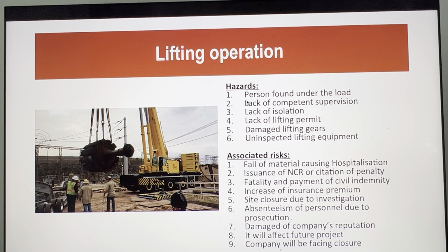In lifting operation, you have person found under the load. When the person is found under the load, that is in itself the hazard. Why? Because there is a likelihood of failure on the part of the lifted load, and when it falls on the people working beneath the load, it will crush them. It will cause injury or even fatality. All right.